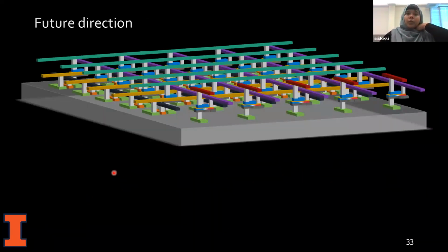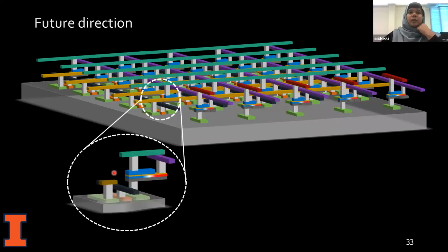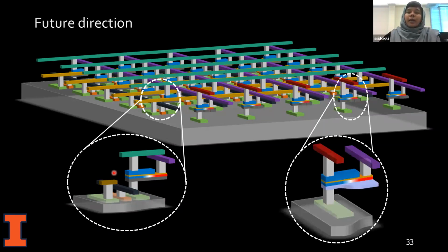So in future, what we are looking forward to is making a system with this kind of analog synaptic devices, where the domain wall moves smoothly inside a wire, and so the resistance change is a continuous function, but it's also linear. And we want at the end of each column a nonlinear activation function generator, also made out of this magnetic tunnel junction. And they are integrated in a continuous fashion on top of the CMOS circuitry. So they can be integrated in the back end of the line of those systems, without actually costing any area in the actual circuit.